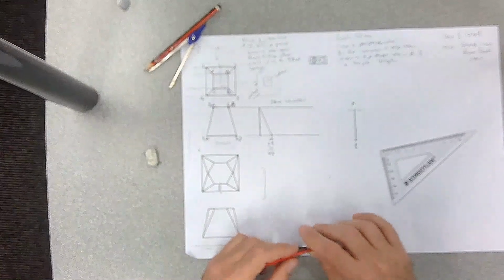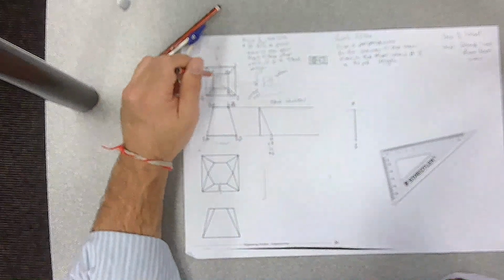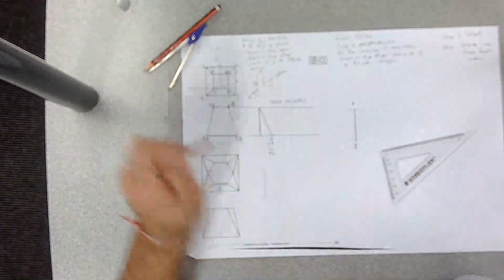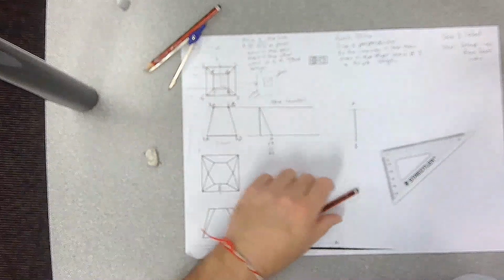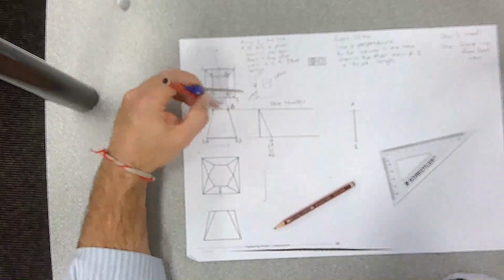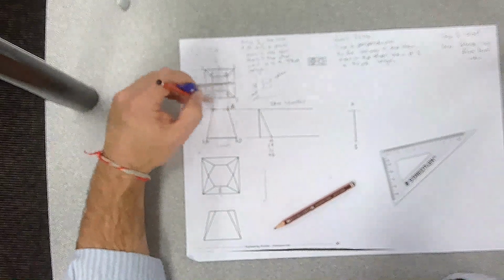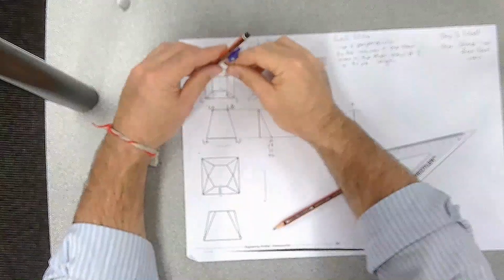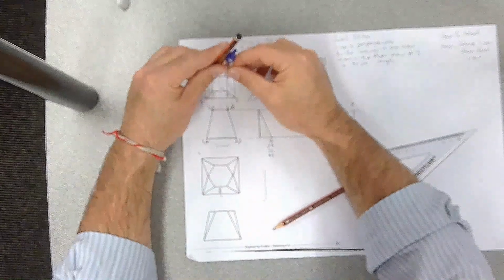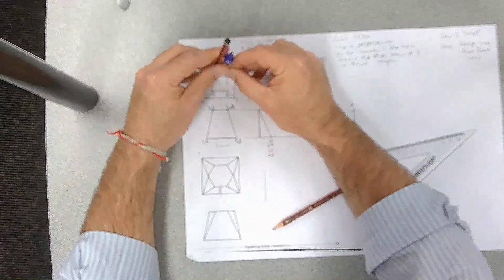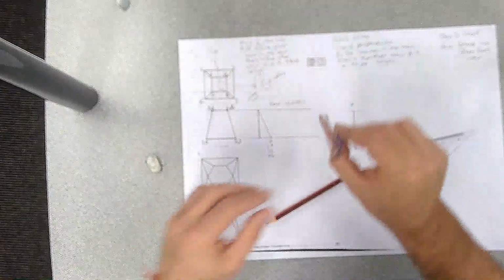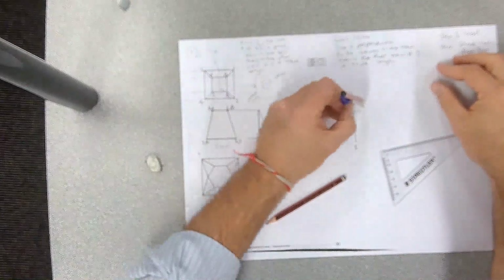Now we need to work out, we're just going to go from A across the top of this shape, because the top is going to be letters and the bottom is going to be numbers. So we're going to go A to B. So is AB a true length? Well, if you look at AB on this shape here, it's perpendicular to the viewer. So we know that in the other view it's a true length, and vice versa. This is perpendicular to the viewer, so you can measure it off either. So we know that is a true length. That's great. We can just put our compass between A and B, and we can swing an arc.